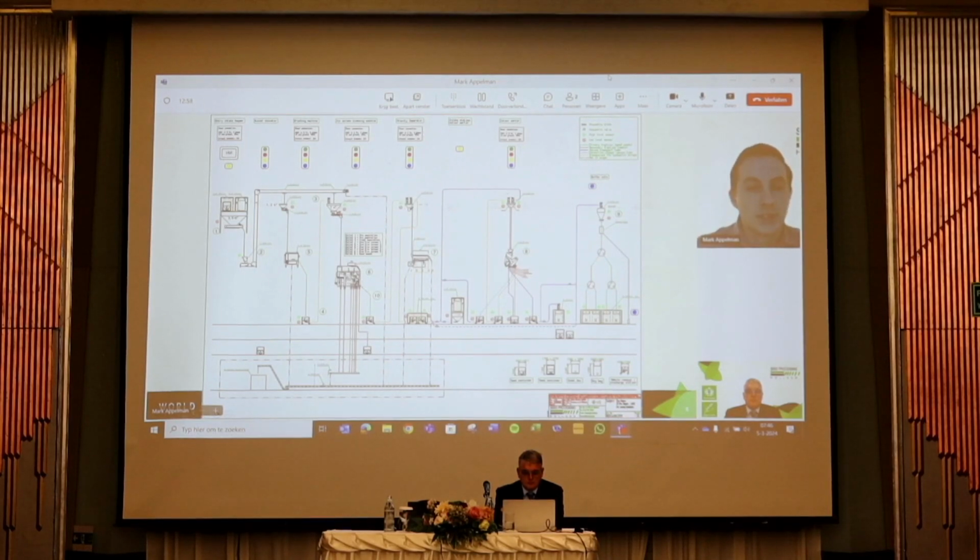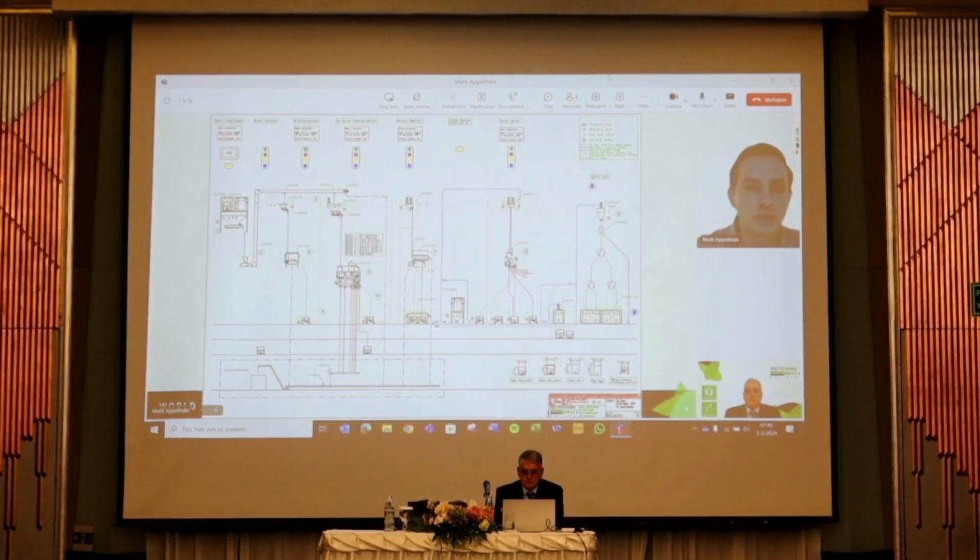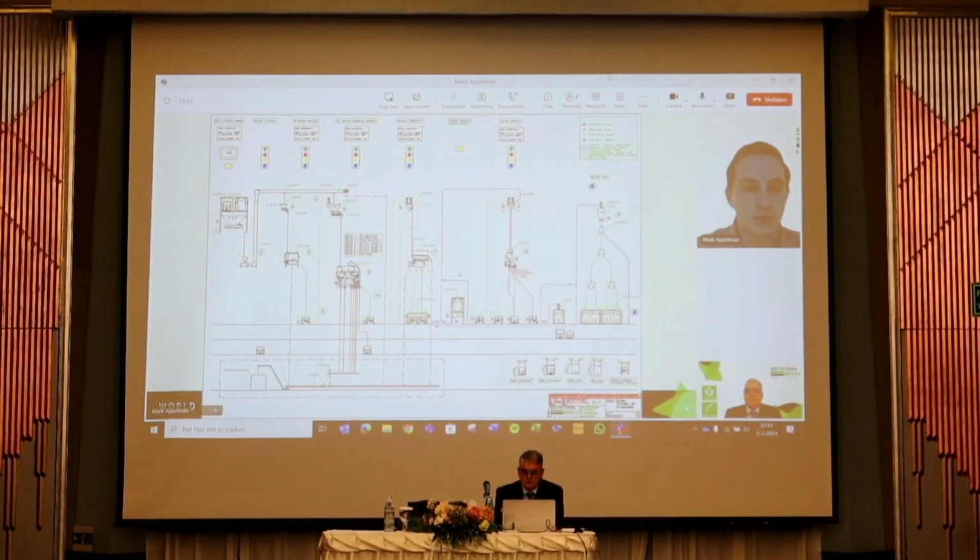All the waste fractions, as you can see here, all the red lines, and the good seed fraction is going to a silo, and the silo is connected to a vacuum transport system to transport all the seeds to the next one. And so you can go through the whole line and can exactly see what is going where, and where we put sensors, as you can see here, the green and the red, around HL, LL, low level, high level.